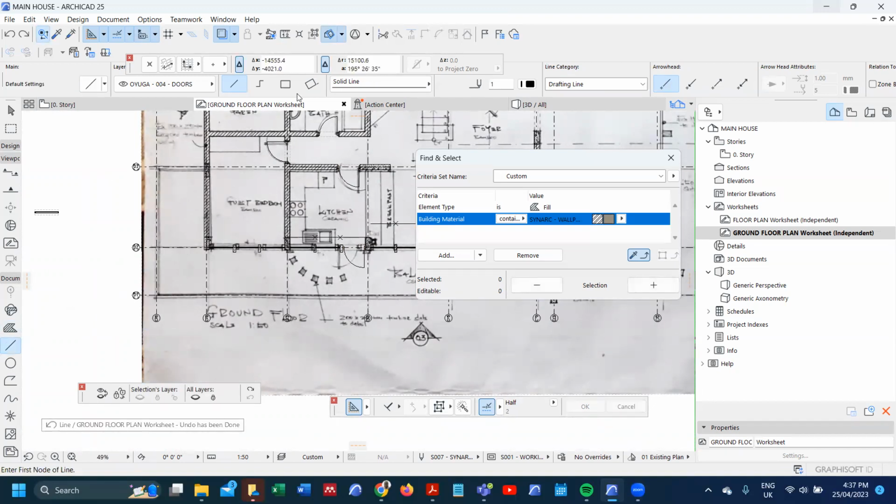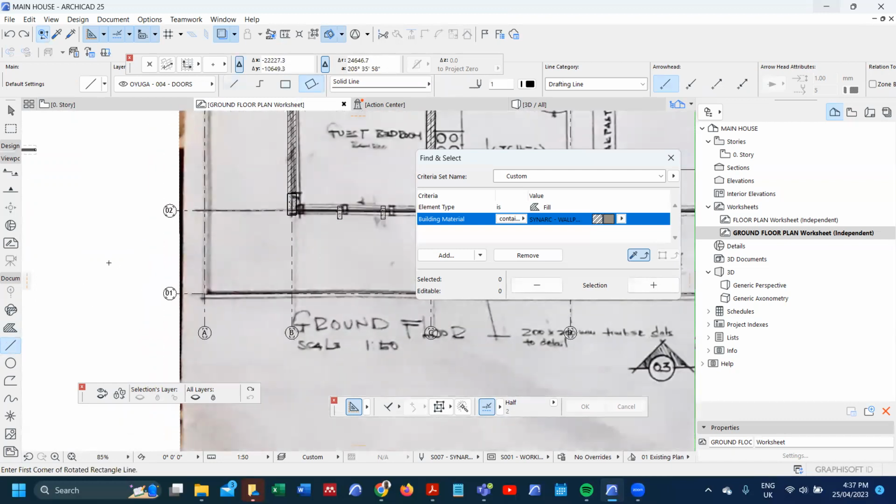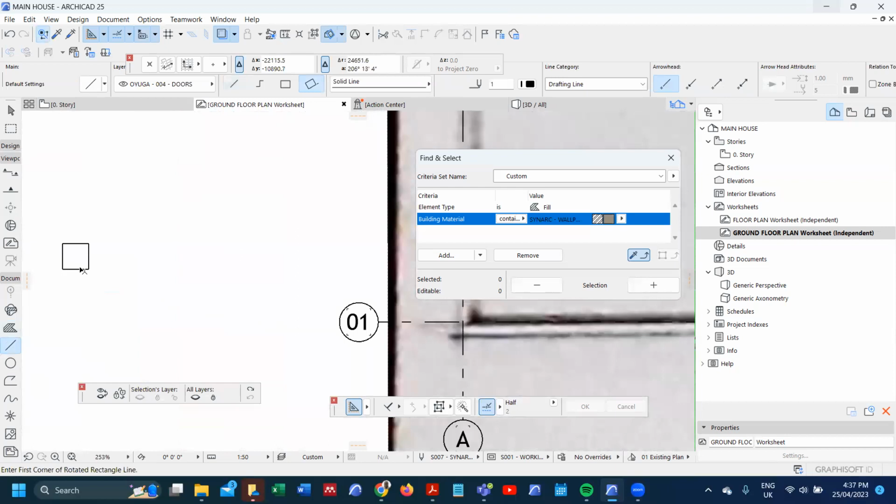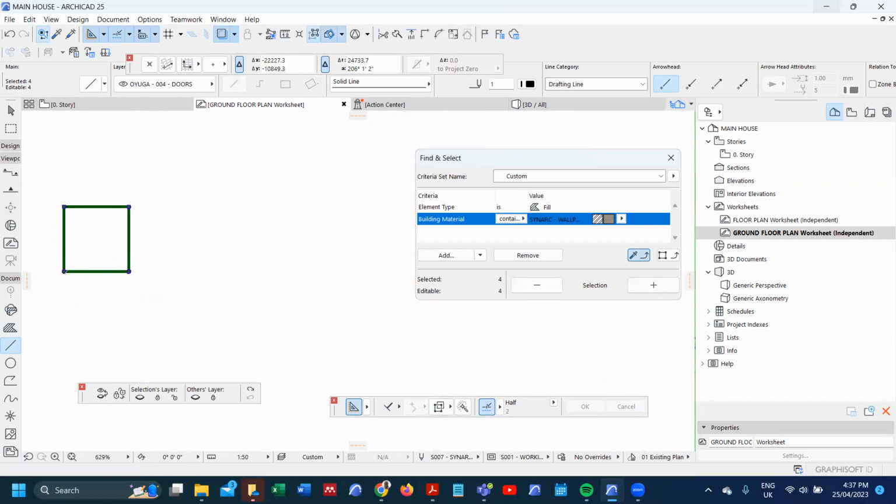So let's create those tubes quickly. They have a thickness. That is something that our friend forgot to write there. Let's give them a thickness of 3 millimeters. Remember, they are tubes.